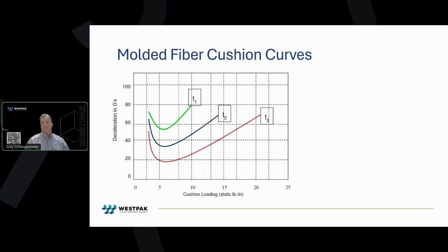Now let's look back at what we were using before for our product from slide 9, which had a critical acceleration. Anybody remember? Put it in the chat if you remember. That's right, 80 Gs. Any of these materials, when properly loaded, would protect the product from impacts from a 36-inch drop, because you can see 80 Gs is all the way up here. So we could use thickness 1 and still be in the 60 G range.